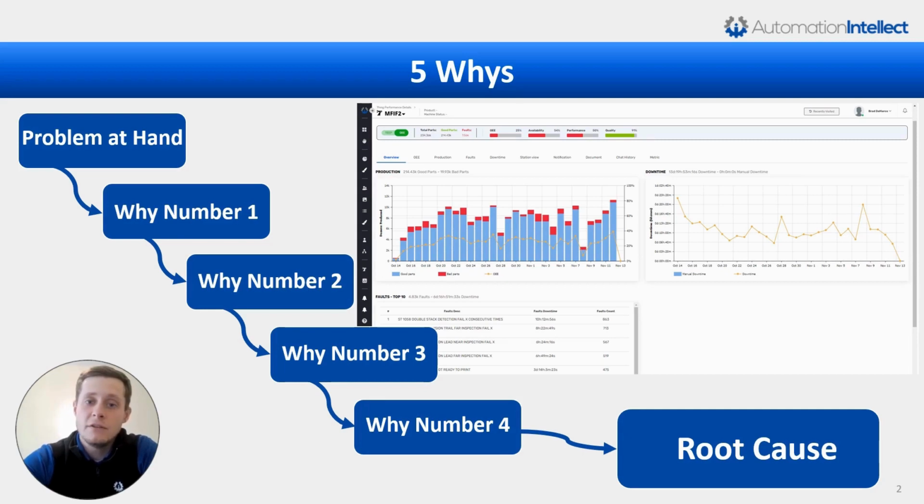So why is the downtime high on machine 1? Potentially because the servo drive overload alarm has occurred 45 times on average. Why is the servo drive erroring so often? Because the servo could be undersized or is at the end of its life cycle. So the root cause takeaway from this would be to investigate and begin corrective action measures on the servo drive.